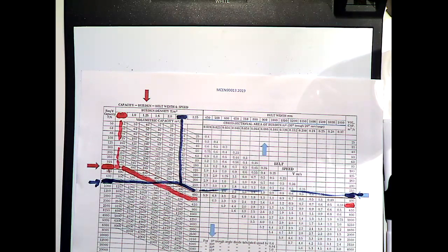Right, now, we've got some restrictions. Because the ore is very abrasive, we don't want it to come at a higher velocity and take out all our chutes and abrade the chute. So the lining on the chutes is going to limit us to about 1.1 metres per second in speed. And because of the coke's dustiness, we don't want it to go faster than 1.1 either.